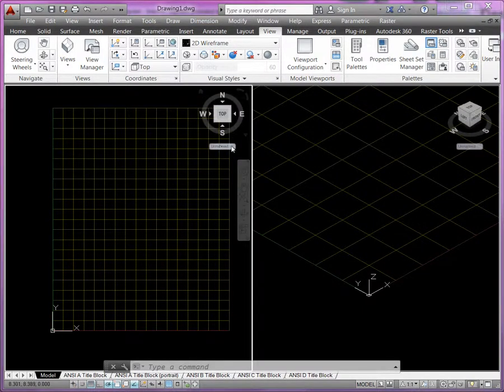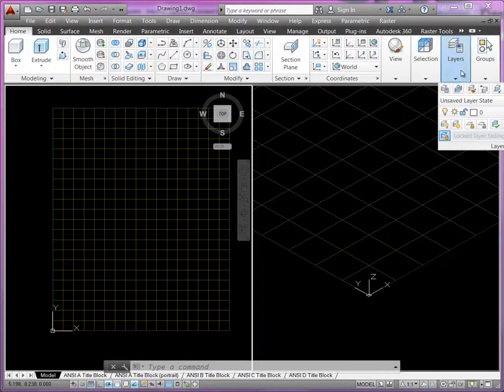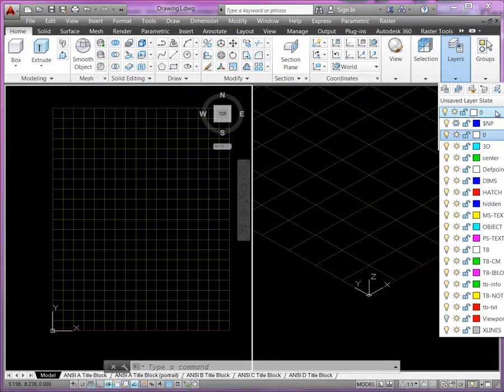And you can see here in the navigator, you can also see what the current UCS is. Now here I want to make sure that it's the world UCS. I'm going to be working on the left side here in orthographic mode, and you can see on the right side I'll be viewing what I'm creating there. So as I proceed, right now the default UCS is the world UCS, right? Where Z is 0, and you can see over here I have my X and my Y. Now I'm going to switch back to home, and I'll take a look at my layers. Right now I'm on layer 0, but I'm going to start in construction line layer.